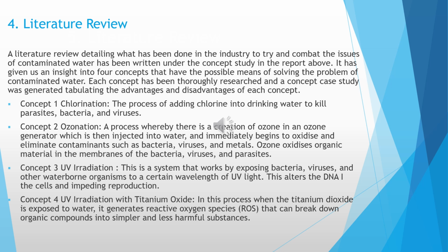The first concept is that of chlorination. This is simply the process of adding chlorine into drinking water in order to kill viruses, parasites, and bacteria. The second is ozonation. Ozonation is the process of the creation of ozone in an ozone generator, which is then injected into water and immediately starts to oxidize and eliminate contaminants in water.